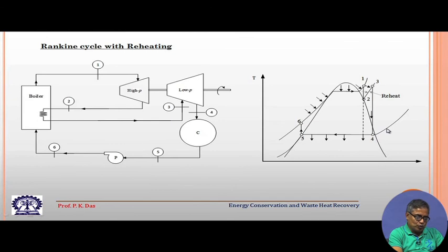That is not good, because then the condenser has to extract heat from the superheated vapor. Second thing, this is one important point, if we have more and more reheaters, then there is extra piping, extra pressure loss, and that may eat away the benefit which we are getting from reheat.